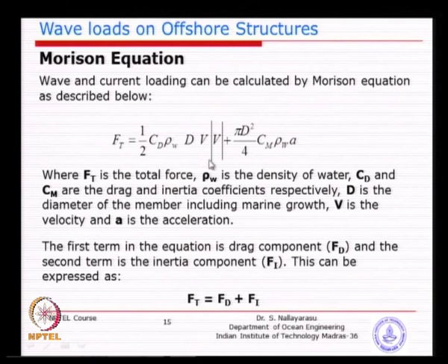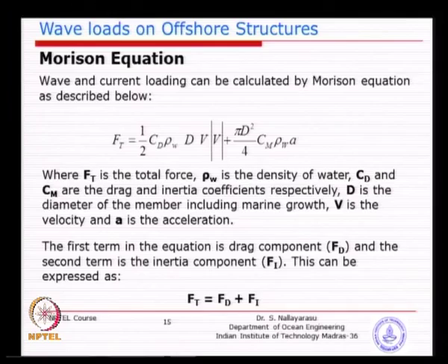But when you have a combined effect somewhere else, where neither velocity nor acceleration is maximum, the combined effect could produce the maximum force, which is what is of our interest, and that is the point of consideration, for which we need to devise a method so that we can automate the process, because it is not one member we are going to calculate, we have a lot of members. I think I have shown you pictures of jacket structures, so many of them, and that is where we need to devise a method.